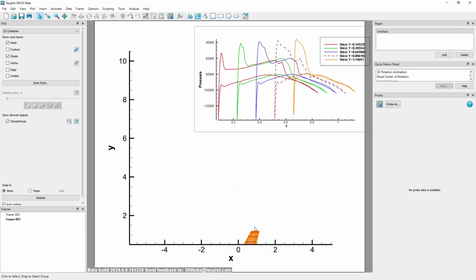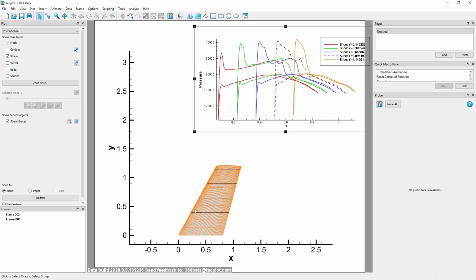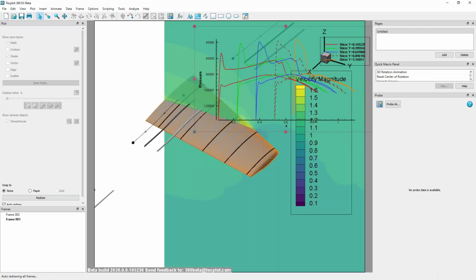So because you do have data in the Z dimension, OpenGL, which is ultimately rendering this, doesn't know whether to show the top nodes or the bottom nodes because we have no Z axis assigned. So if you do want to see a top-down view and you have a change in Z, it would be best to view it in a 3D plot and top-down. So I hope that answers your question. If it doesn't, we can again follow up via email or phone call.